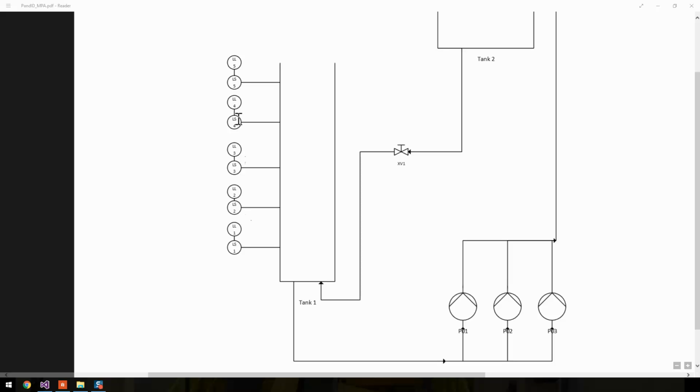And we've given them some example names: level switch, level light. Each of the sensors has its own light connected directly to the sensor. So on the model, the light will light up if there's water above it, and this sensor will send a signal to the PLC.